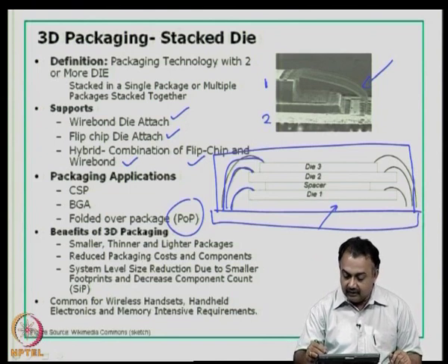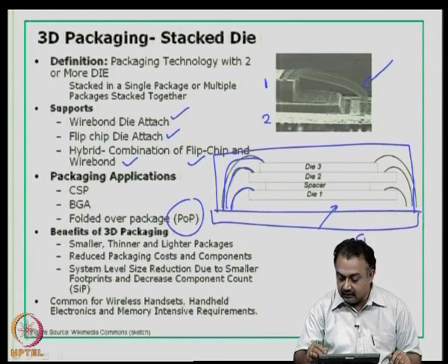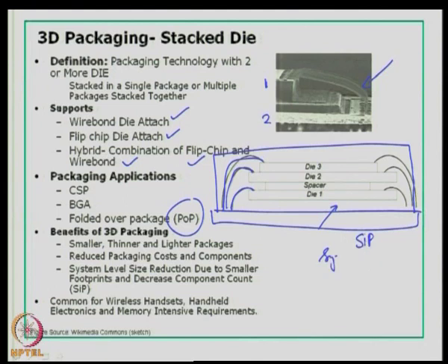So, typically these kind of packages are known as SIP, system in package. SIP is generally not available off the shelf. You have to custom build a SIP package, and the application areas for these are wireless, handsets, handheld electronics and memory intensive requirements.